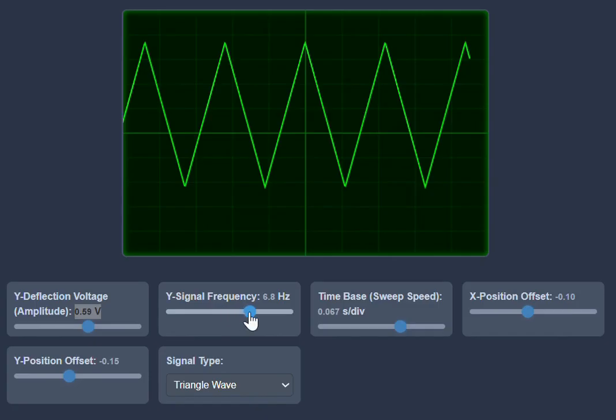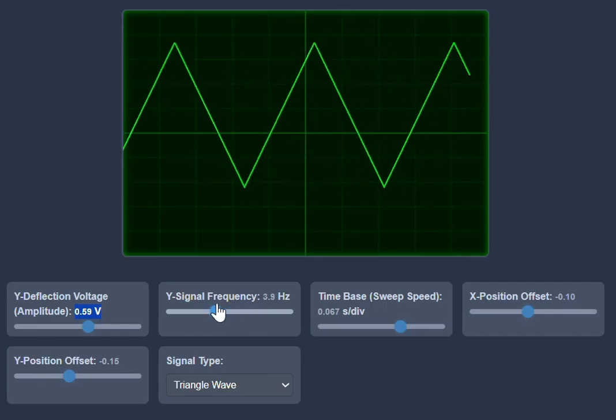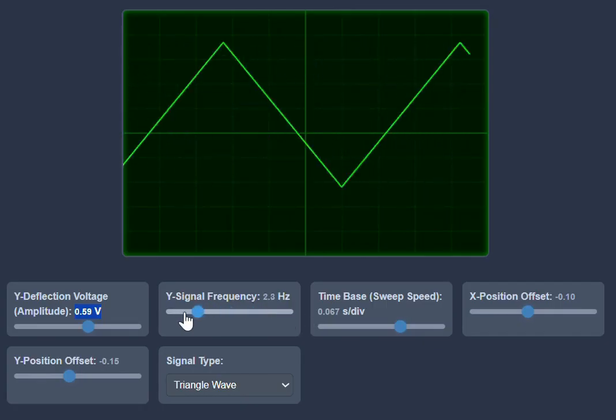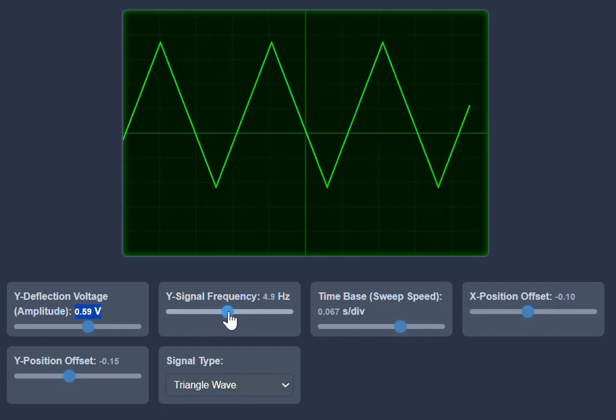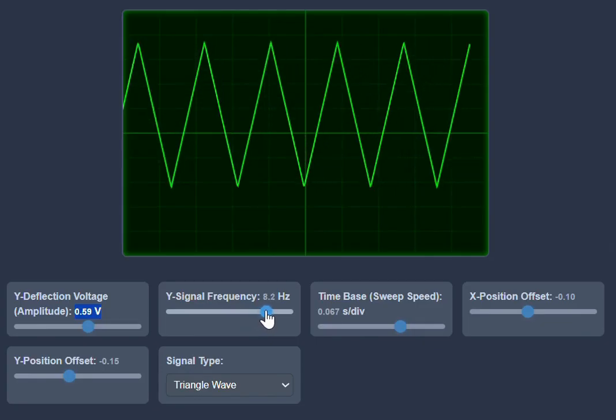How fast the signal changes vertically along the y-axis. You can see the signal changes vertically here. To increase the frequency and measure the time period properly, we use the functionality keys on the x-axis, where the divisions measure the time period.